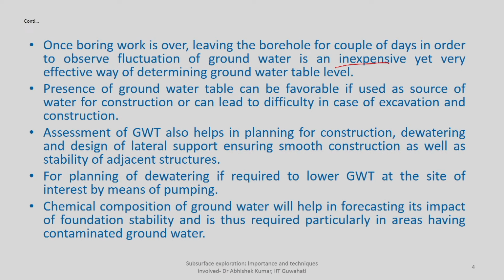So, what will happen, along with the water, the soil from the adjacent site will also start moving, and slowly there will be a void underneath the foundation of the adjoining structure, which will lead to failure of that structure also. And moreover, it is not only about the stability or safety of the adjoining structure. Finally, the water mixed with the soil, that is slurry, is also getting filled up in your excavated area. That will make it difficult for you to continue with your exploration program, or if you are going for laying of foundation, again it will cause difficulty, and it will also compromise the safety, because from the surrounding soil there is seepage going on.